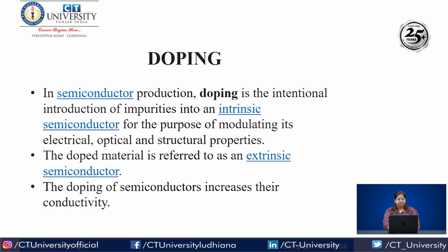Next is doping. In semiconductor production, doping is the intentional introduction of impurities into an intrinsic semiconductor for the purpose of modulating its electrical, optical and structural properties. The doped material is referred to as an extrinsic semiconductor. The doping of semiconductors increases their conductivity.